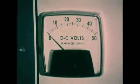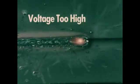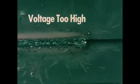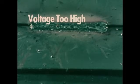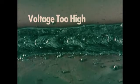If the open circuit voltage is increased to 35 volts, there is excessive spatter, and the arc sound is now sharp and rasping. The load voltage during welding goes up to 26 volts. The bead has an irregular ripple, and the edges of the bead suggest poor fusion.